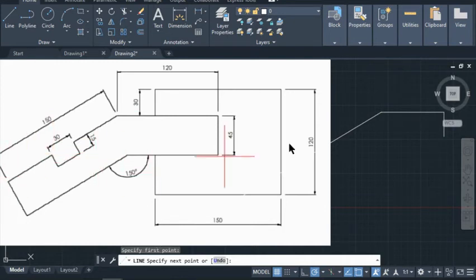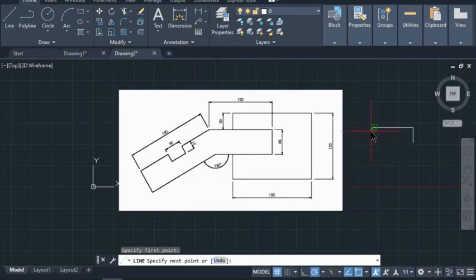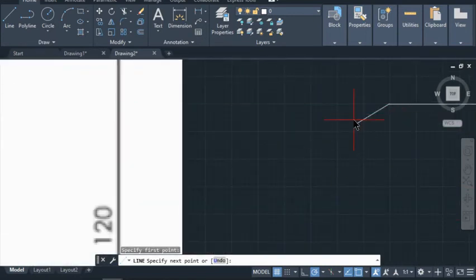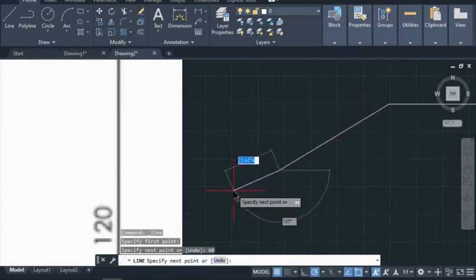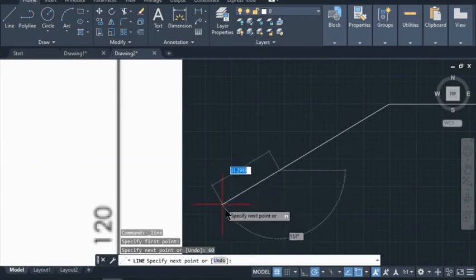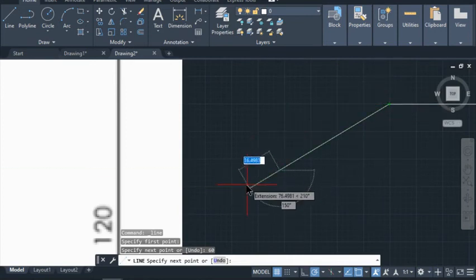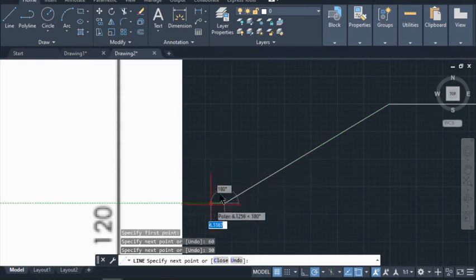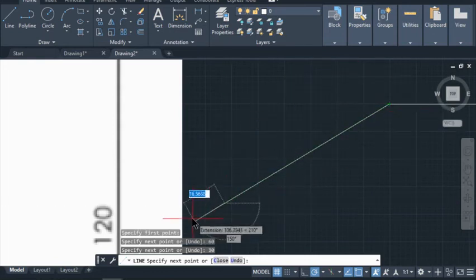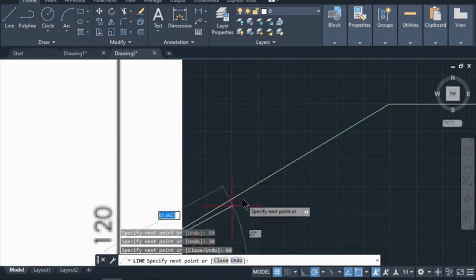Okay, so let's go over here. That's what I have right here. I'm just going to go down here and make sure that I have that be 60, and then I hit enter. Now I'm going to go 30 this way. I don't have my snap line turned on, so I have to go to the end here without clicking. You can see that a rectangle or a square shows up, and then I go back down here. Now I have that green line to follow. That will be my snap line, and I'm going to put in 30 to have that section in the center there. Then I'm going to do the same exact thing. This time I'm going to go down 60, enter, and I hit escape.